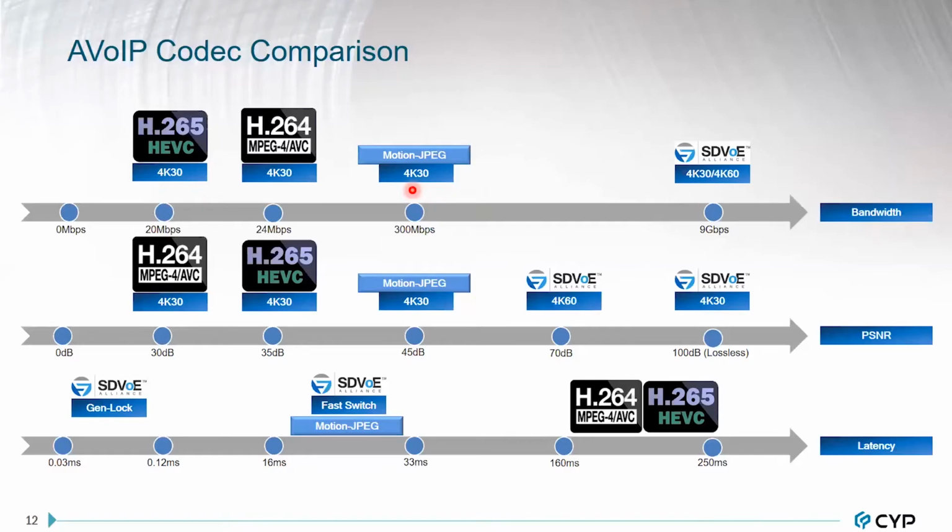The H.264 and H.265 codecs transmit the same resolution using less than 30 Mbps. To transmit the same resolution over low bandwidth, compression is required. The main downside of compression is a loss in video quality. There is a value used to analyze video loss, named PSNR.